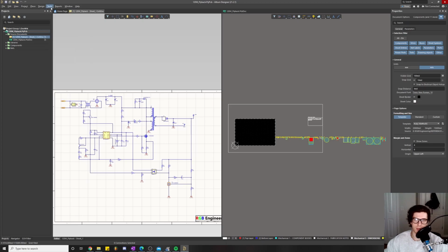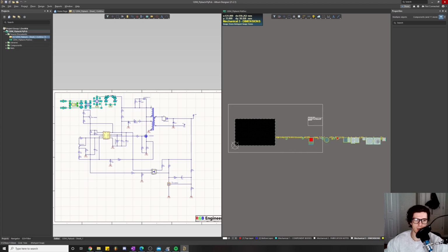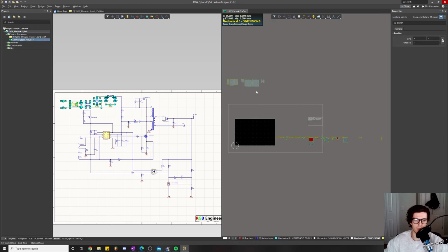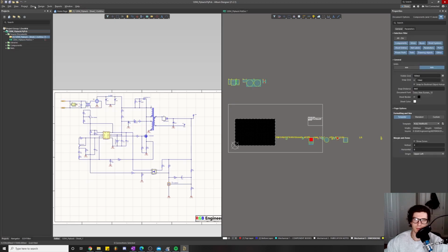This is what it looks like when it's selected; it has a little square around it, which is kind of hard to tell. And then we'll hit select PCB components. This is going to enable us to highlight groups of components all at once. Then they're all selected, so on this side we can just drag them over here, and we're going to start grouping components one by one.